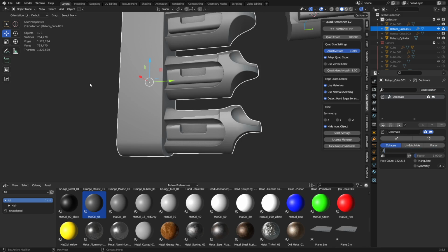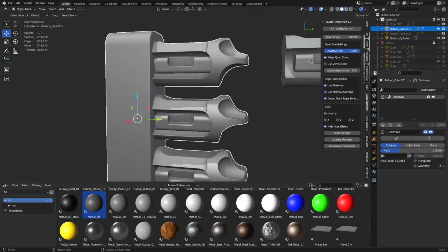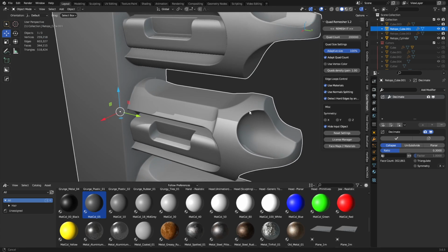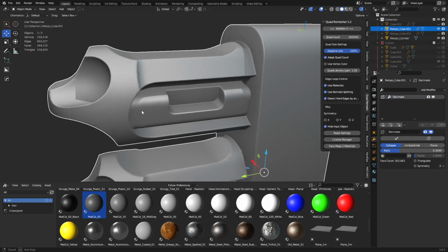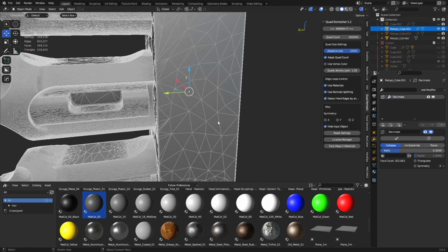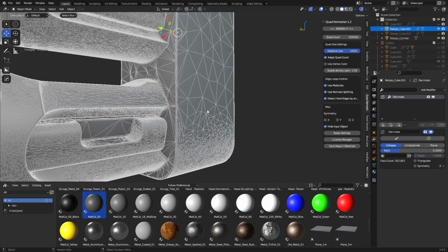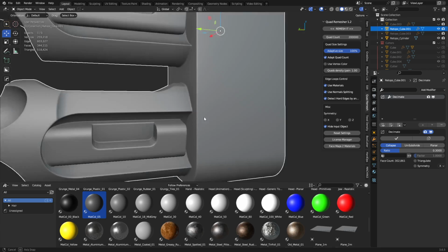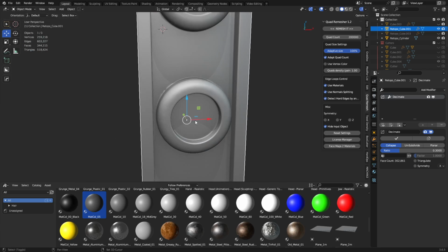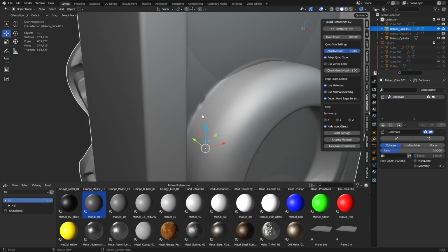Let's just do 0.3, and we'll go from a million triangles, 700,000 faces, and we'll see what 0.3 ends up with here. And it's taking us down to 344,000. And the shading doesn't really change, guys. It's pretty much the same setup here for the most part. What it's doing is decimating mostly the flat planar surfaces first, and then it'll start working away at the edges a little bit. But it tries to maintain the curvature, which is quite good. So you could still potentially bake this thing out.